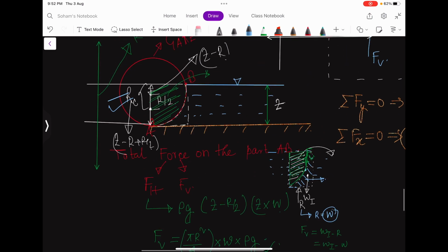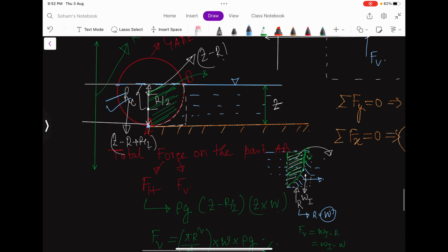For both the cases, when you don't have this upper surface, just extend this free surface and look at what is the end point of the fluid domain. It is this. Now just consider that I have the fluid all over this gate up to this point. So this point is very important. Then you have to calculate the weight of this much part only, that is above the domain.